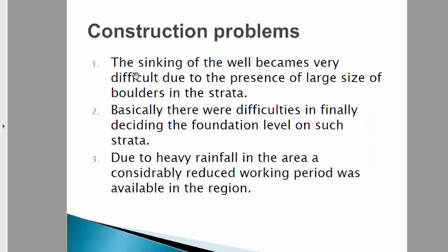So what construction problems were there? Let's discuss the problems faced during sinking of this foundation. The first problem was that sinking of the well became very difficult due to the presence of large boulder strata, because in the river there are many types of boulders. Due to the boulders, the well does not sink properly. So the difficult part is sinking. There was also difficulty in finally deciding the foundation level in such strata.